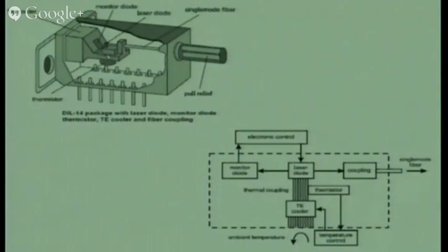That means within the setup, within the device itself, I must incorporate many other fabrication aspects. So what are those fabrication aspects? This laser diode is mounted on a heat sink, and at the same time we have a thermistor which monitors the temperature of the junction itself, right? So it monitors the temperature. If I want this to be controlled, that 30 degrees centigrade should stay 30 degrees centigrade, I must look for a feedback mechanism there itself.